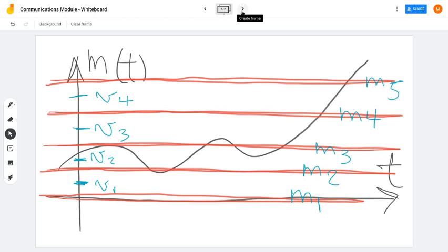So if we have a sample over here, and then we have sample here and there, all these samples are discrete in time, but yet their amplitude can take any value. The amplitude is continuous. And this is what was used in the analog pulse modulation. But right now in digital pulse modulation, we're looking for something different. This amplitude should be quantized.